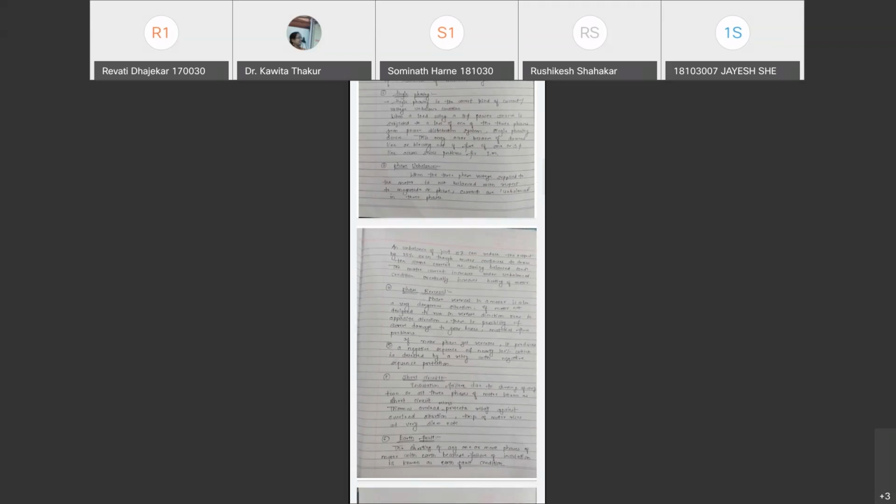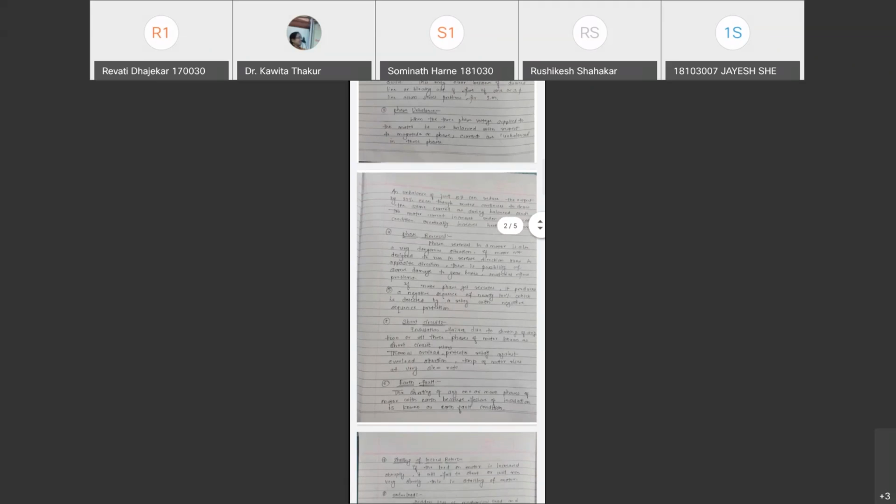In this protection, this accounts for all thermal processes, starting and running at the normal overload conditions. Its function is to operate the motor within its predefined temperature withstand limit, and the temperature is measured by thermistors. Second protection scheme is protection against unbalanced currents. The motor will draw excess current because of single phasing, hence the winding will be overheated. This may damage the rotor structure. So a negative sequence relay is used. In phase fault protection, differential protection is adopted for small motors and overcurrent relays are used.